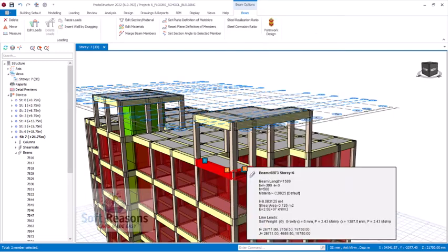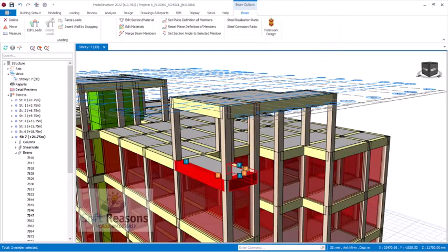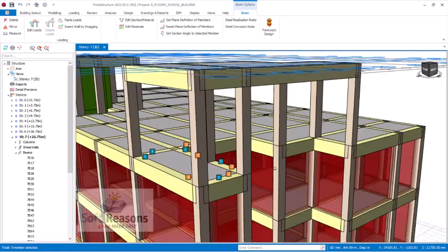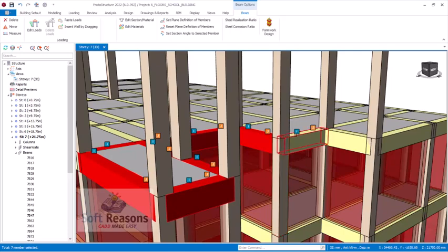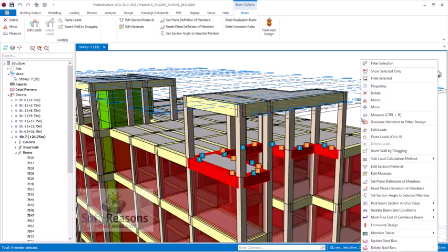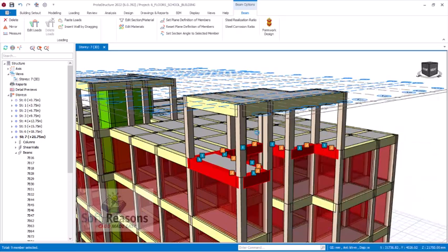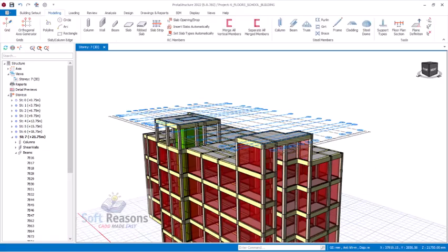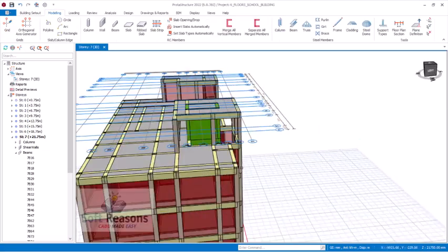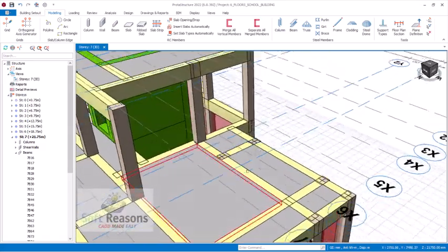Hold the control key to select as many beams as you wish, just like this. You can see we may not have a wall load somewhere, or we'll delete some of that. Right click, I select paste options, so you can see we now have a wall load right there, just like this. Okay, same thing applicable here.